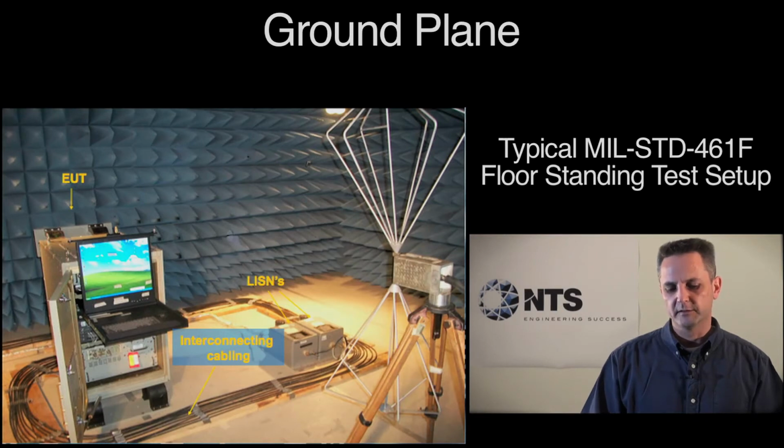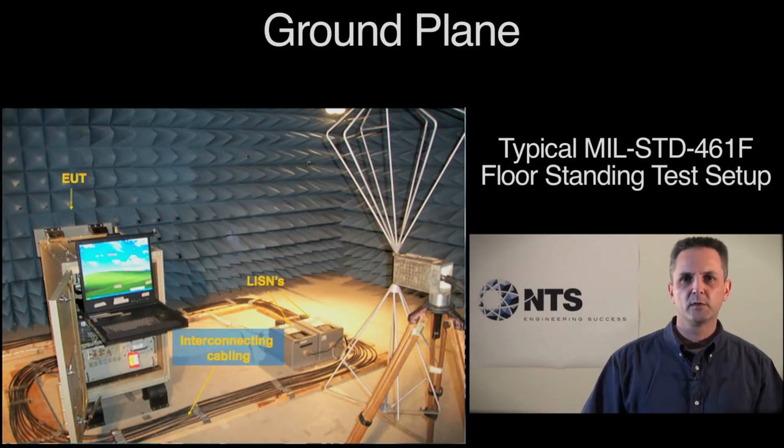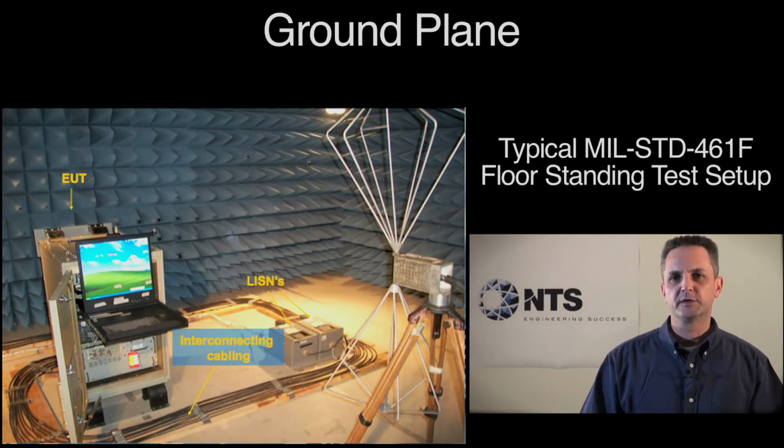You'll actually see the LISNs on the floor connected to your power lines, connected from there to the equipment under test. This would be your standard test setup used for a certification test, virtually every certification test in 461.